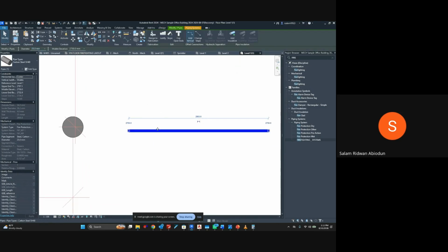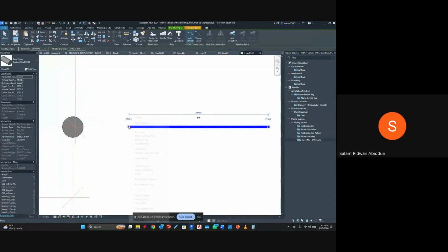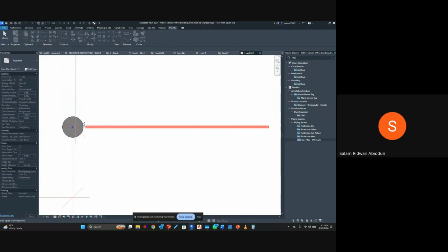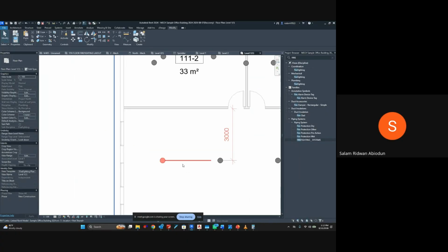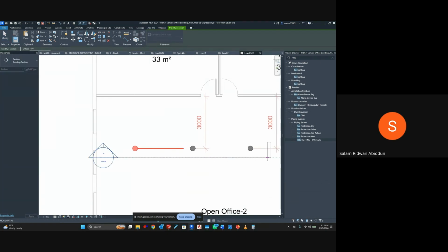Okay, so I would like to align this to this, then move it very close, then press connect into. So it's giving me one or two errors. Okay, so the dimension, because it's constrained, don't forget. Anytime you are seeing an error like this on Revit, don't just click and say this is not working. No, read what is in there. I've constrained it with a dimension before. Do I want to delete the dimension? I say yes. So I don't need the dimension. Now it's connected.